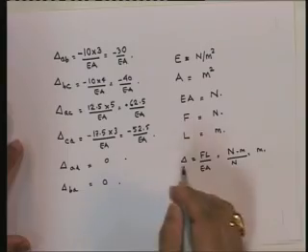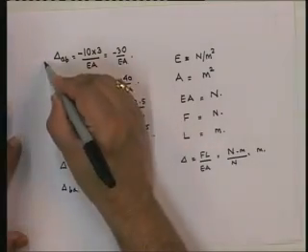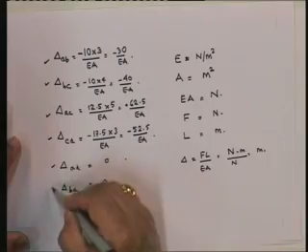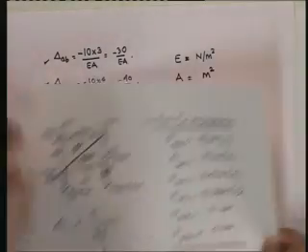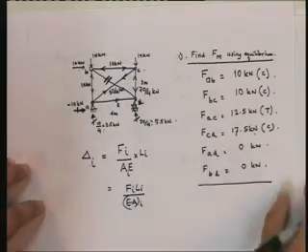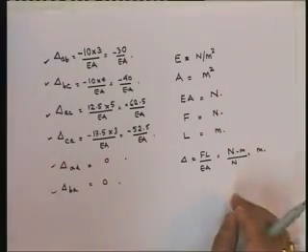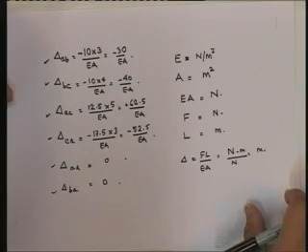Okay. So I have found out the deformations in all the members. What are these deformations due to? These deformations are due to the loads that are applied on the structure. Okay. So now, I have done that. Now what is the next step? Let us first go through all the steps and then I will put it all together. Okay. So the next step is what? Next step is actually finding out the forces in all the members, okay, due to the redundant force.